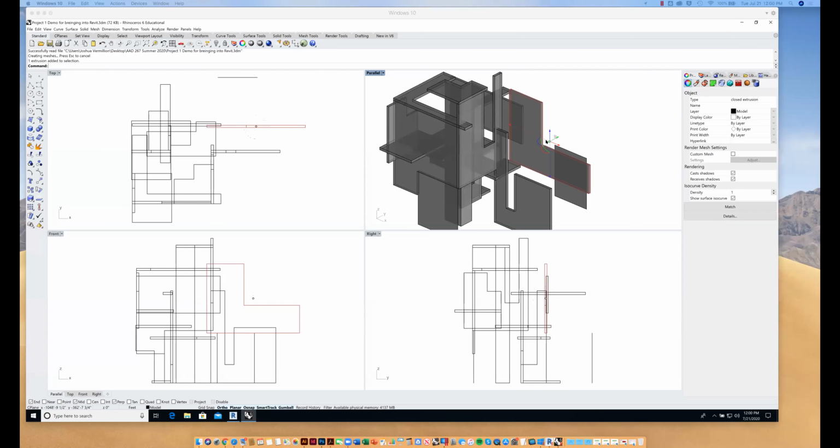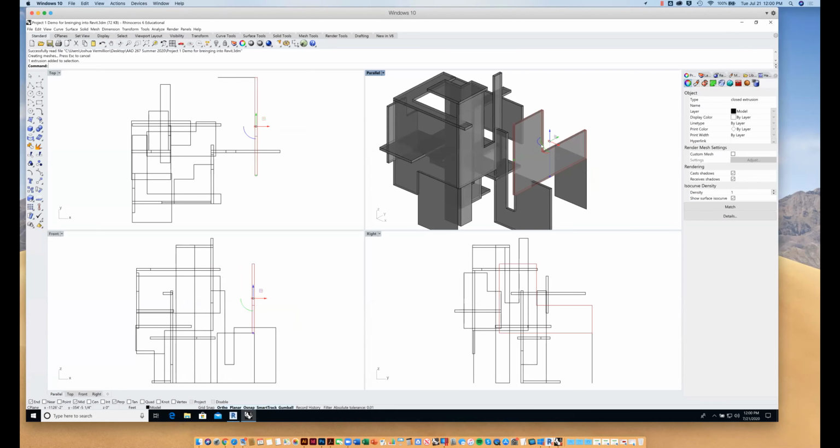Right, so here's the Gumball. And when I see this 90-degree sweep right here, the rotation sweep, I can click on it. I could type in literally 90 degrees and it'll rotate 90 degrees, okay? Around, in this case, the Z axis, or 270 if I want to rotate it in a different orientation.